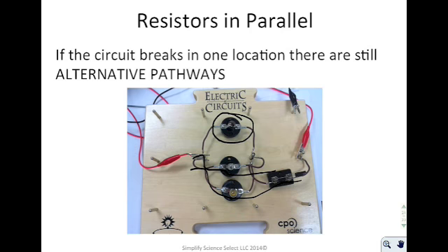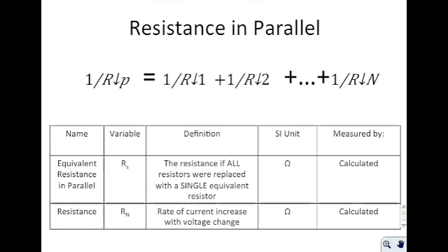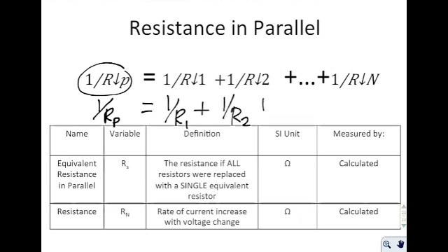Okay. Next, whenever you are calculating the resistance in parallel, you get the formula 1 over Rp equals 1 over R1 plus 1 over R2 plus dot dot dot. These arrows right here are just trying to show you that those are subscripts. So the resistance in parallel is equal to 1 over the sum. It's not just adding them anymore, it's adding their inverses. And that may seem like a small distinction at first, but it really is a big deal.